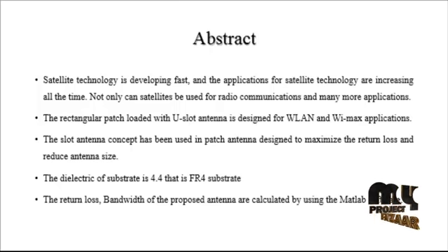The rectangular patch loaded with a U-slot antenna is designed for WLAN and WiMAX applications. The slot antenna concept has been used in patch antenna design to maximize the return loss and reduce the antenna size. A dielectric substrate of 4.4, that is FR4, is used in this fabrication. The return loss bandwidth of the proposed antenna is calculated using MATLAB software.